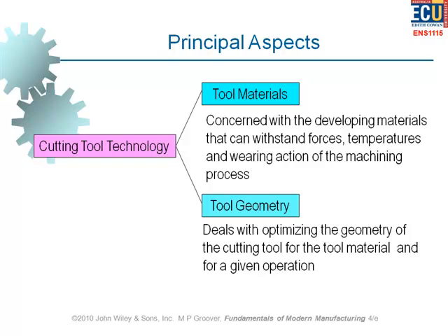Resultant surface finish, which depends on what? Machining parameters and also the geometry of the cutting tool, which is the tool nose radius, right? So, as you can see, what you get to some extent depends on the geometry of the cutting tool as well. So it's important for us also to make use of the right geometry for the cutting tool